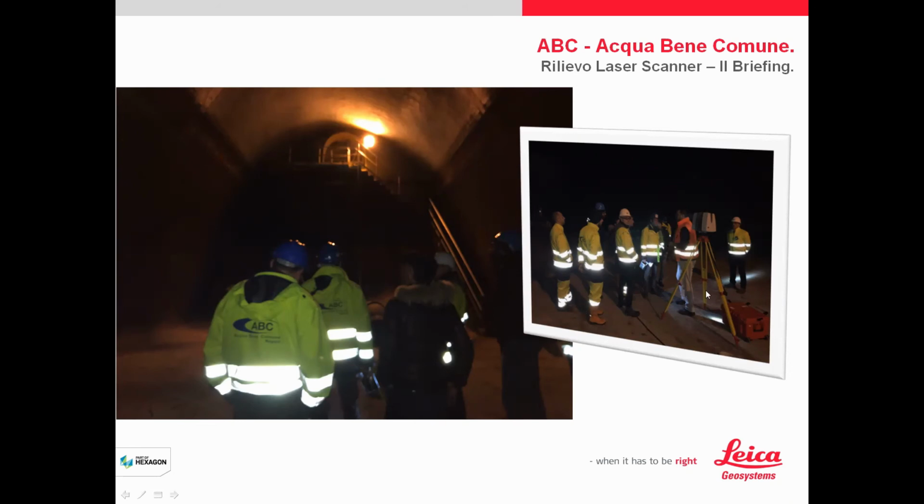And this is the scanner. Again, I used a P-series. I love the P-series because it has a topographic method by dual axis compensator. For me it is very, very important to be sure about the verticality of the point cloud, for my mentality, of course. But I repeat this because today the new sensors do not have a topographic Z level, but they have a dynamic Z level that does not have the same precision, and probably you can end up with a point cloud that is not leveled. Okay.